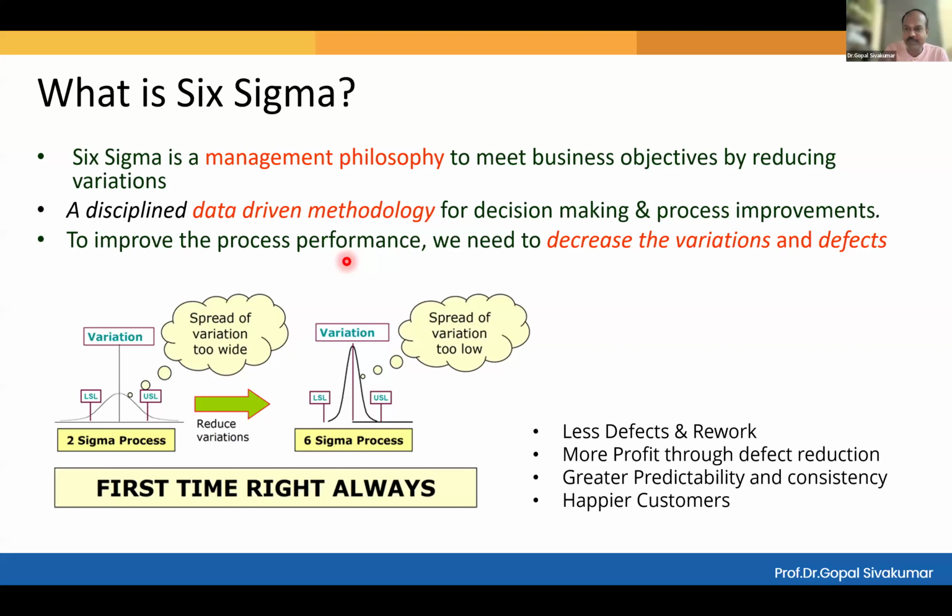In place of one sample, you could take 2 or 3 samples. Normally for blood collection, people don't take 2 or 3 samples, but in your company, you can always take multiple samples. A group of samples is known as a subgroup, and the number of samples inside the subgroup is known as subgroup size or sample size. If you plan in this manner, a sample size anywhere between 2 to 25 will be a fantastic sample size. We have to deep dive into all of this; it is a separate subject by its nature, and you have to spend enough time.